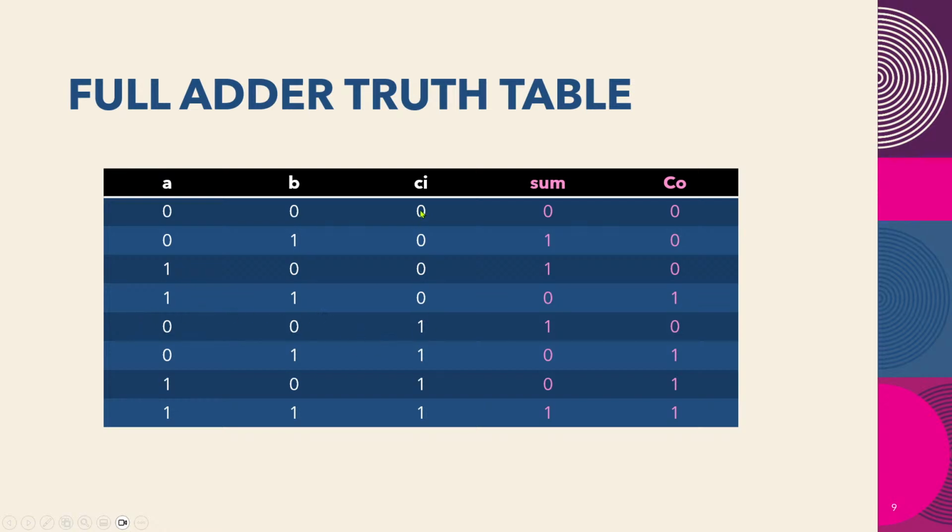So you could use the carry in operation. You could use the same logic that we did before for the sum here. Take the inverse of that based upon the value of carry in, and then do something similar for the carry out.